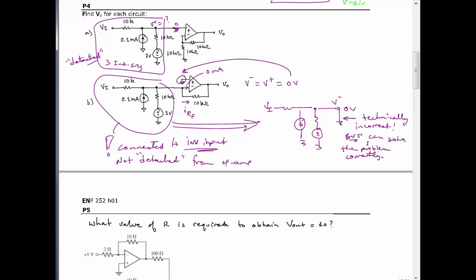Okay, so it's not true that it's grounded. There is no current that is flowing from this network here into ground. It's flowing toward the OpAmp, and it's actually flowing through the 10K feedback resistor. It is not going to ground. But because the voltage at the inverting input is equal to 0, if you draw a different network, which is this one here, and you ground that V minus node, you will find the same voltages and currents flowing. This current right here mainly, I'll call it I.